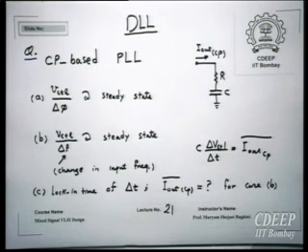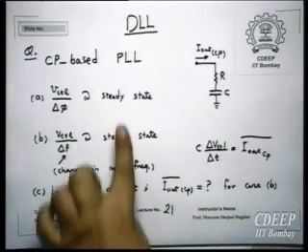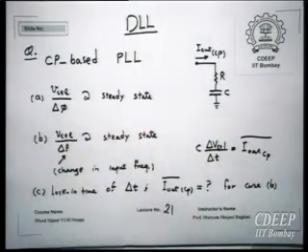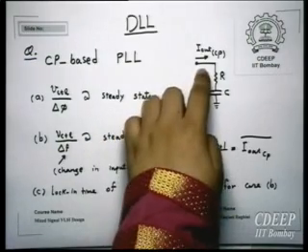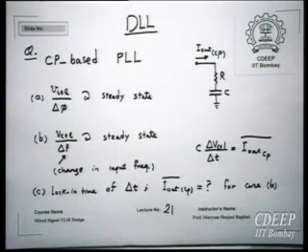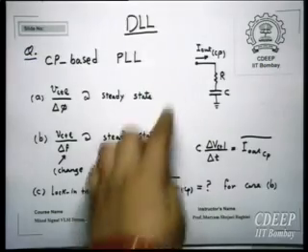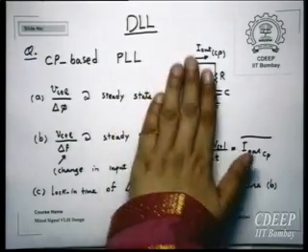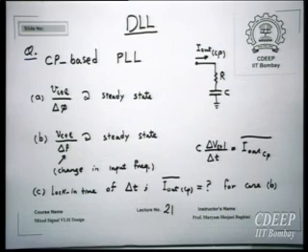this charge pump circuit at steady state is unstable, right? Because at 0 frequency, if you give a constant current, this output will be infinite. That is the reason actually delta phi becomes 0. Because the input of this circuit at the steady state is 0, therefore this will maintain some voltage. That is obvious, right? Now, if you want to calculate lock range, then what will be the proportionality constant of this circuit at steady state? There is no proportionality constant.